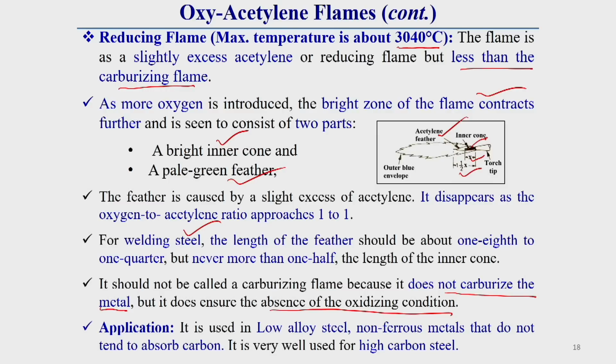It is generally applied to low alloy steel, high carbon steel and non-ferrous materials, especially those materials which do not tend to absorb carbon. For such materials, this reducing flame is widely used.